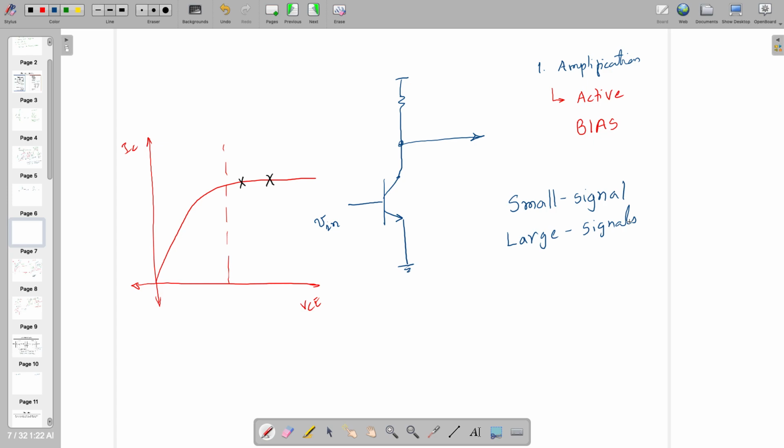So okay. If there is an amplifier whose gain is 10, if input is 1 millivolt and this side supply is 1 volt and this side is 0, the output is 10 millivolt. But if I give an input of, let's assume, 0.5 volt, output is not 5 volt but it's 1 volt, so it gets saturated and this is a large signal.